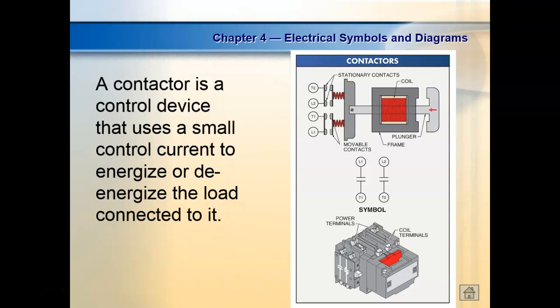So everybody okay on the relays? Y'all understand relays, right? So relay has two types of contacts, and these would be the contacts. These would be drawn like this. These are normally open. So that means if the relay is not energized, which is a term we're going to use a lot.